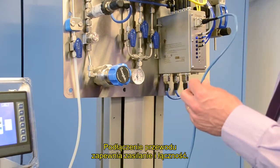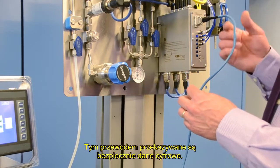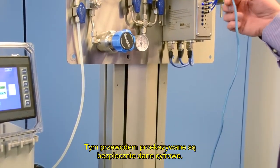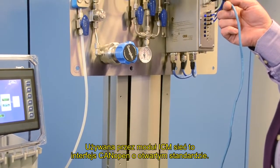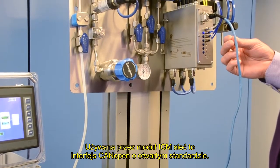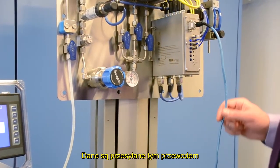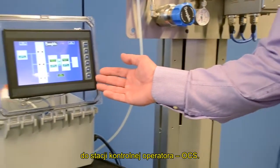Both power and communication are present inside this wire, and this intrinsically safe digital data makes its way through this cable. The network that is used by the ICM is an open standard CANopen interface. That data makes its way down this cable and ultimately over to our operator control station.